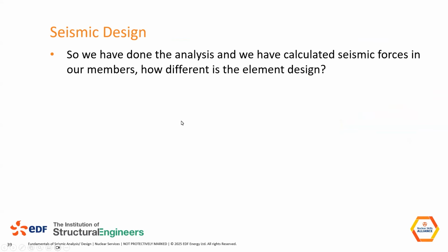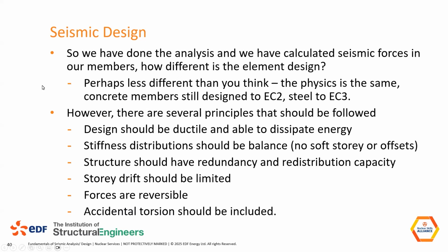Okay, and then seismic design. Once we've got the analysis, we've got the forces, we need to think about seismic design. Again, a whole topic on its own. I think the main thing to note is it's not that different. Seismic design, if you think of Eurocode 8, generally points you back to Eurocodes 2 and 3 for concrete and steel. So we have an element, we have forces in the element, and the designs for the moments, the shears, the axial forces are generally designed in the same way.